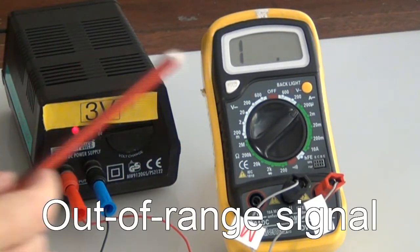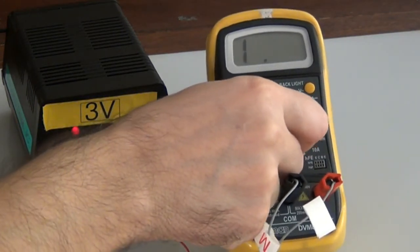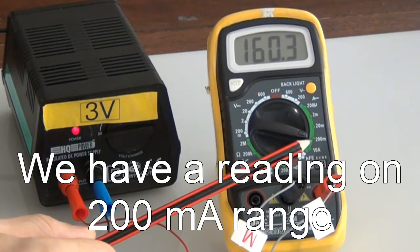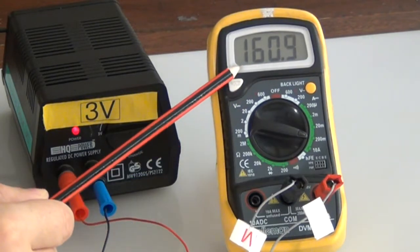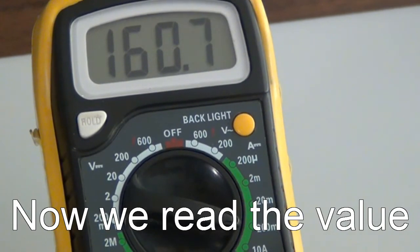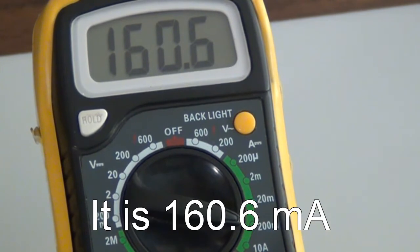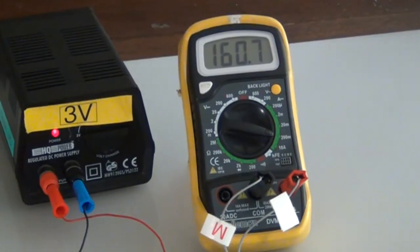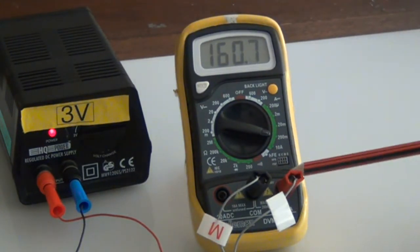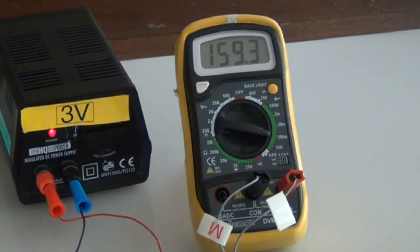When we switch on, we see an out of range signal, so this means we have to choose another option, another higher selection, and now we have a reading on the 200 milliamp option. Now we read the value and we will see that it reads 160.6 milliamps. We also use the COM and right hand side terminal.